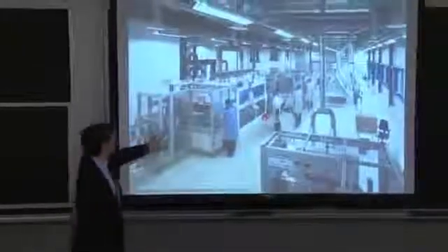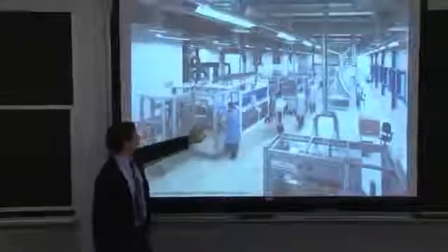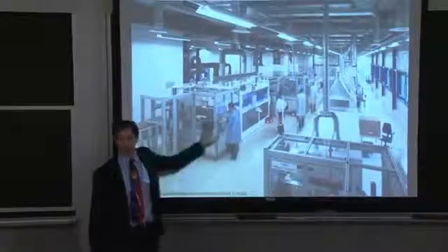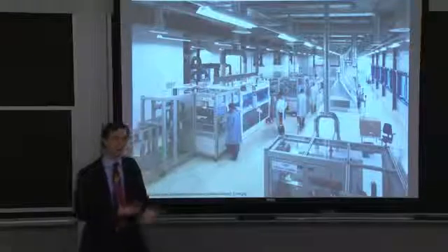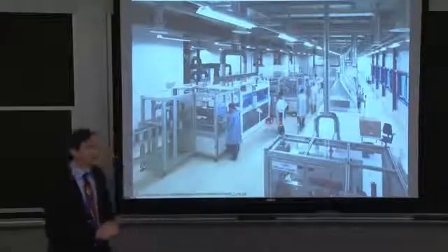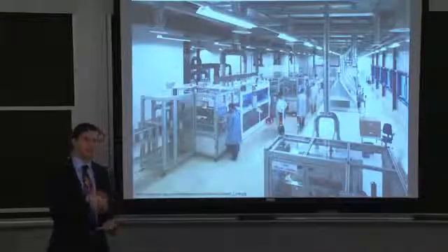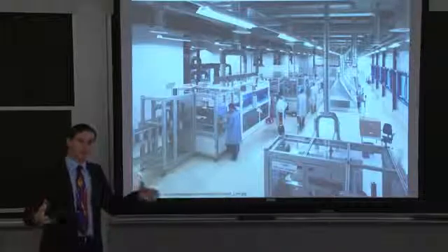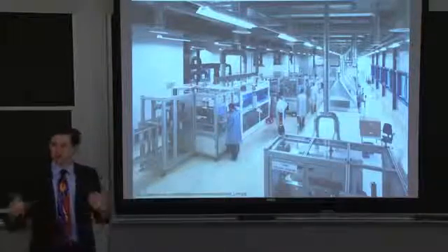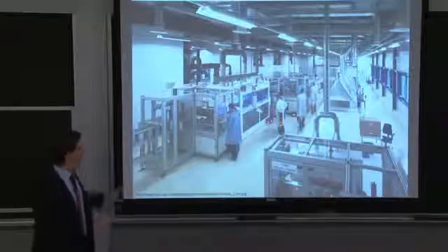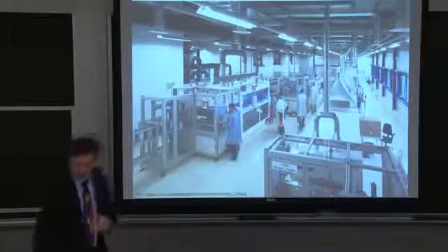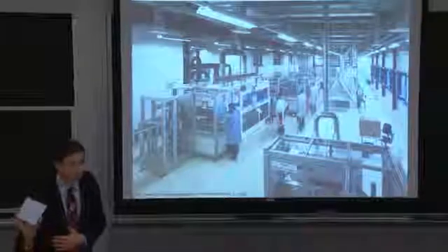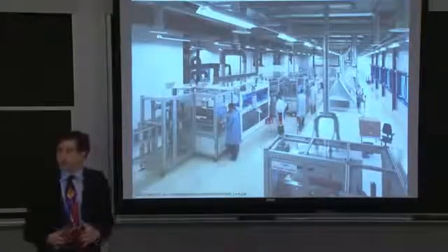Whereas in wafer fab, it was pretty dirty. In cell fab, it looks pretty clean. You have a combination of these inline processes, like this one shown here, where you have wafers on conveyor belts moving through lines, and batch processes, where little robots pick and place, line wafers up inside of crucibles or boats, and then insert them into furnaces for batch processing. So this is the crystalline silicon cell fabrication. In on one side go bare wafers like this, and out the other side come fully processed solar cell devices.